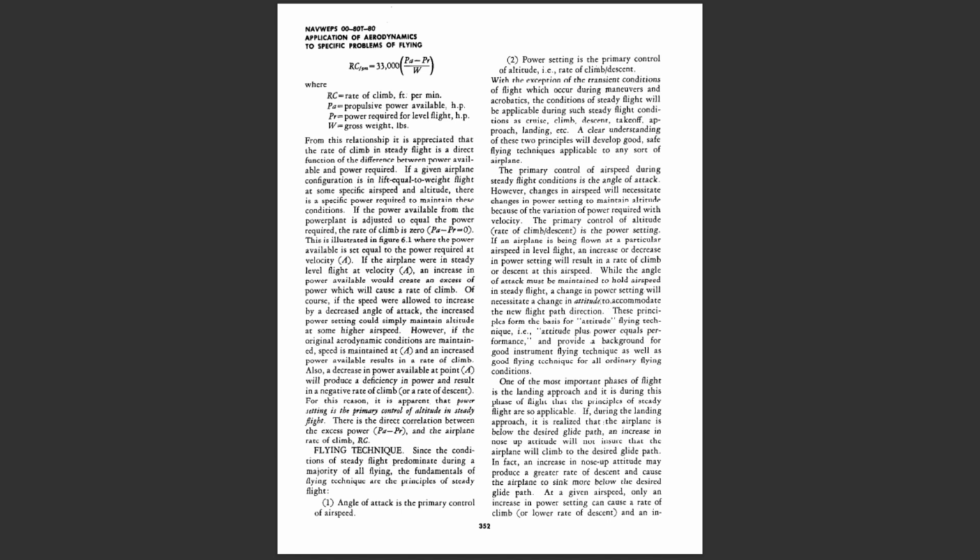One of the most important phases of flight is the landing approach, and it is during this phase of flight that the principles of steady flight are so applicable. If, during the landing approach, it is realized that the airplane is below the desired glide path, an increase in nose-up attitude will not ensure that the airplane will climb to the desired glide path. In fact, an increase in nose-up attitude may produce a greater rate of descent and cause the airplane to sink more below the desired glide path.